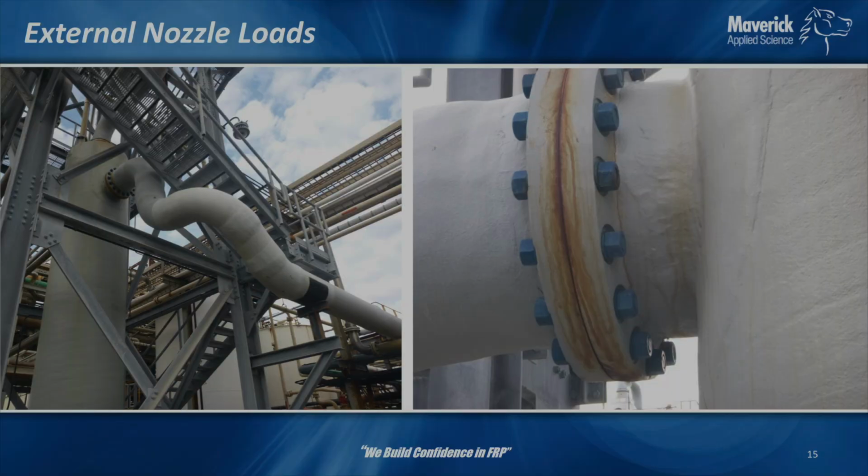And in our inspection, what we found is this is actually the back side of that nozzle. Here's your tank, probably looking from this side, probably looking from that stairway or catwalk over there. This is cracked all along the back side here. Now it's a pretty robust flange. You can't tell me that that's under designed, but still you've got all this load hanging off the end of it. Really, that needs to come into play when we're doing pipe stress analysis.